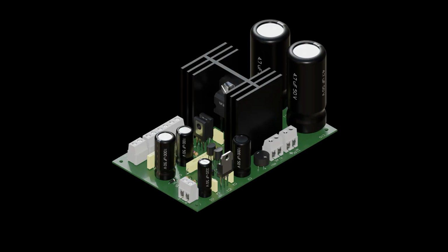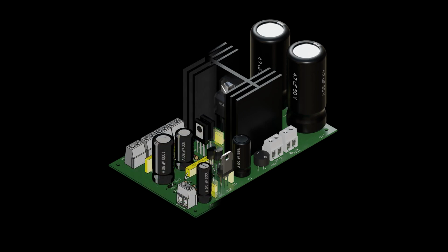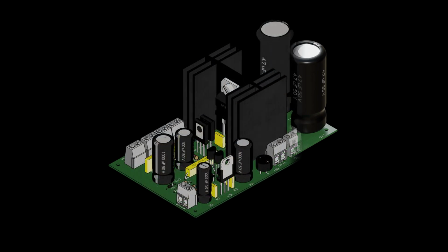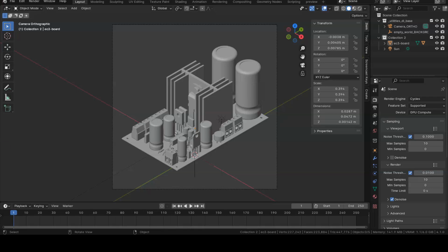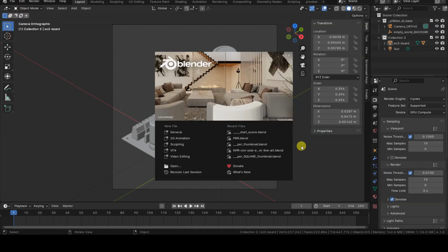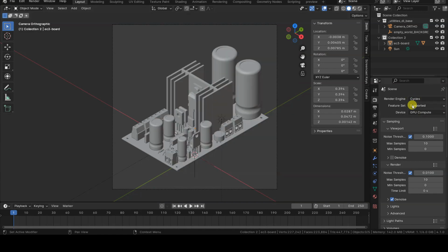I start by showing you the difference between the rendering obtained by importing the 3D model, which already has its PBR textures connected to a principled node, and the non-photorealistic rendering, which uses only the base color texture and a suitably configured principled node. This tutorial was created in Blender 4.1, and the rendering engine used is Cycles.